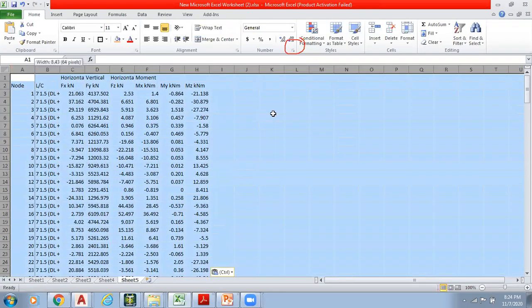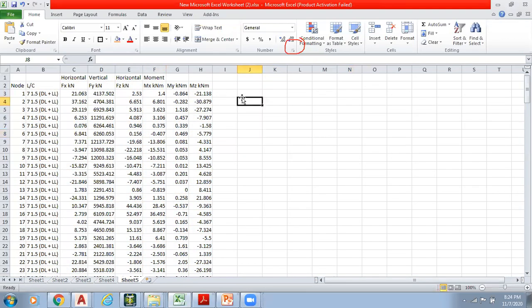Now, I don't want to take all these bending moments. Before taking these bending moments, if you can remember, we had given the pinned supports. We have given the pinned supports for the retaining wall locations. When we ask STAAD Pro to give the reactions, STAAD would be giving us the reactions for the fixed supports and also the pinned supports. But we don't want the reactions for the pinned supports, right? We don't want them because we are not designing the foundations, and those are not even columns. Those are just supporting points which are connected to the retaining wall.